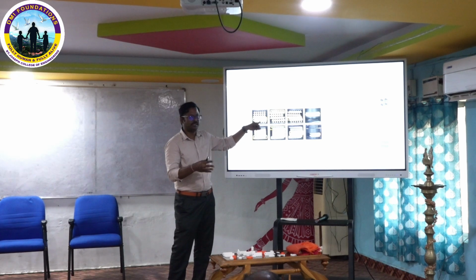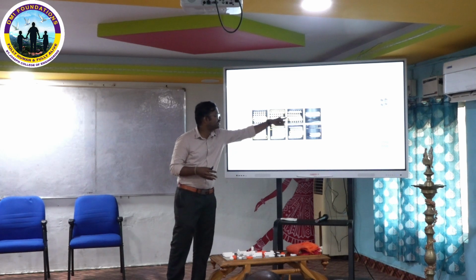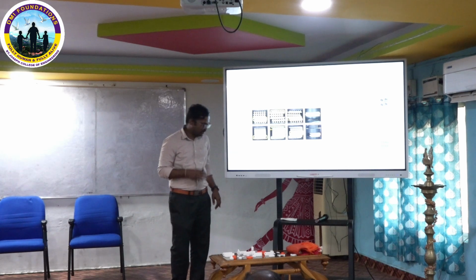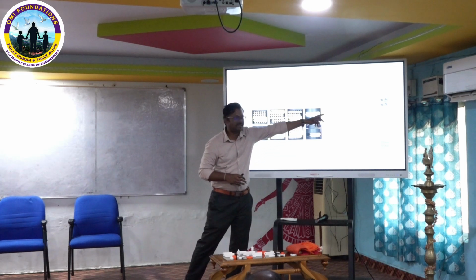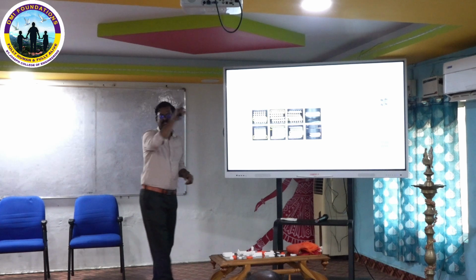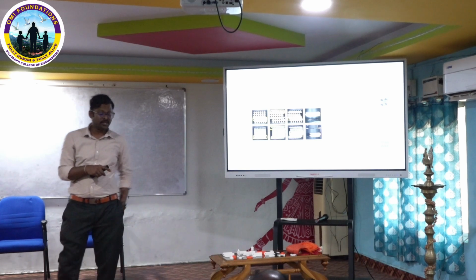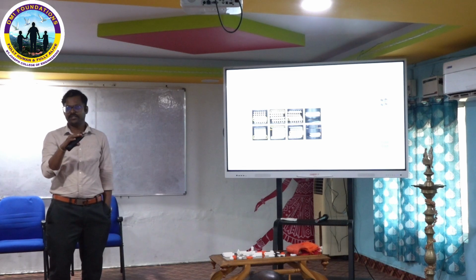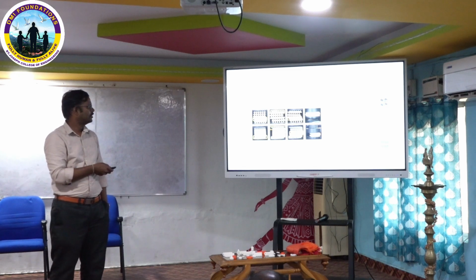First it showed progressive failure. First this layer of unit cells gets deformed, then another layer, another layer. That kind of progressive failure I get. So it impacts my stress strain curve. You can see the fluctuation in the plateau region. Okay. This is the reason for the stress fluctuation that I already explained.